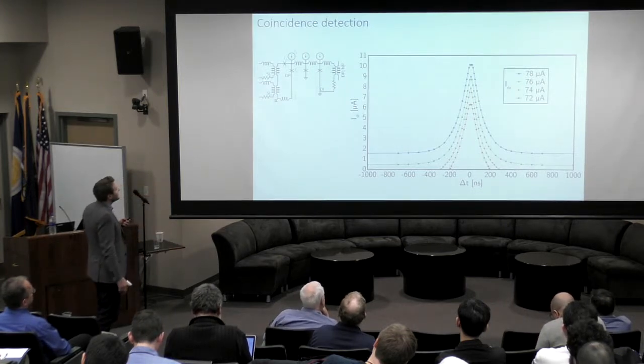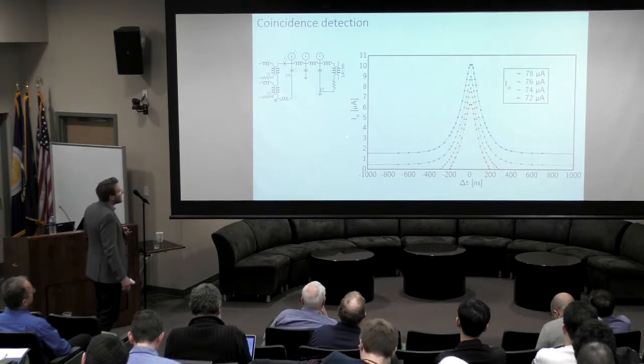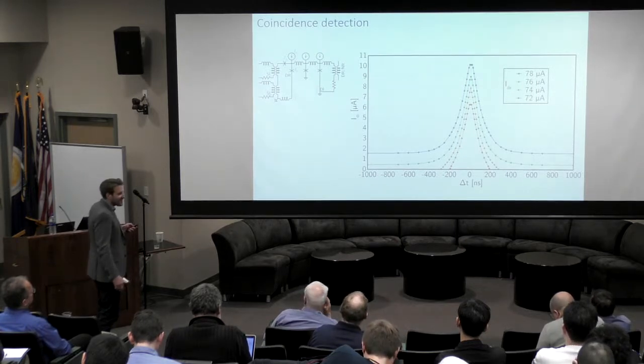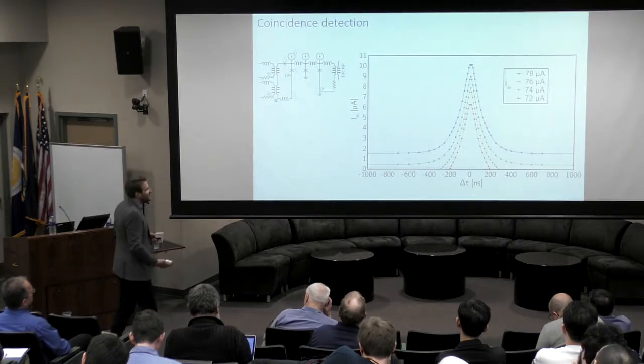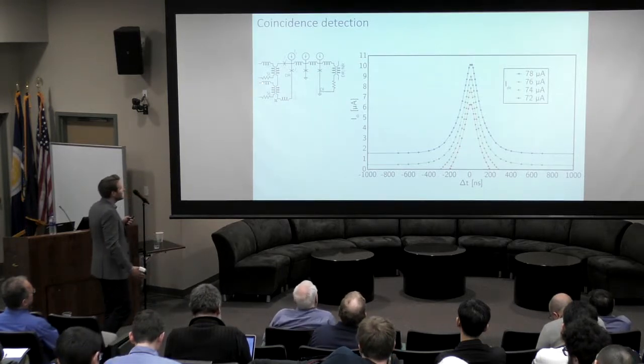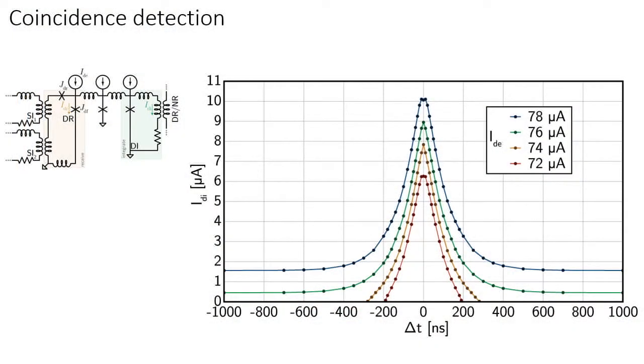So if you have two different synapses coupled to the same dendrite, now what I'm plotting is the amount of current added to the dendritic integration loop, that's the post-dendritic current, as a function of the delay between the two synapse events. And you see it has, in this case, an exponential decay because we've outfitted each of these with one L/R time constant, which I'll remind you can be set in hardware across a very large range of values. And importantly, we can tune the response to this with the dendritic bias current, which is a lot like the synaptic bias current. It provides us a dynamic means to reconfigure our circuits and allows us to have access to various different learning mechanisms now at the dendritic level rather than the synaptic level.